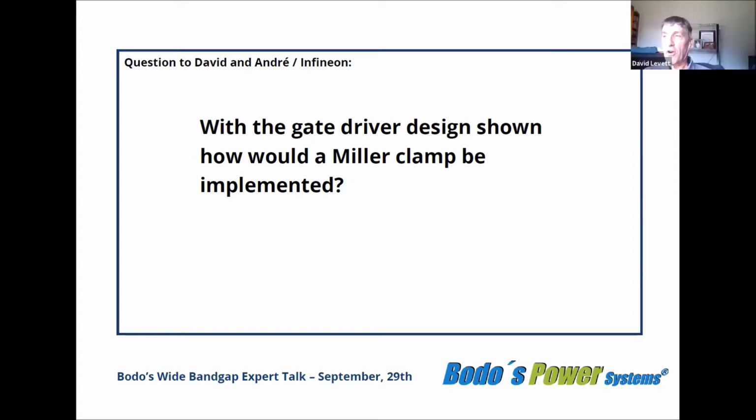Okay, well, thank you. I'll try this one. This actually is a very popular, I'd say common question that we have. If you use a single gate driver to drive multiple parallel devices, you have to somehow separate or put impedance in the auxiliary source. Otherwise, we always joke, we call them teenager electrons because they go where we don't want them to go. They will flow through the auxiliary source rather than the power source. And this is not a good thing.